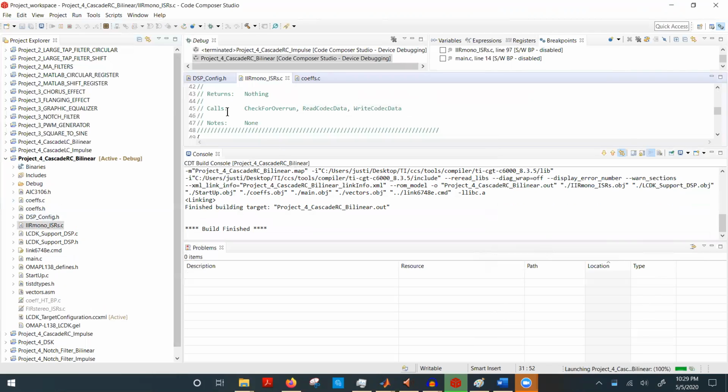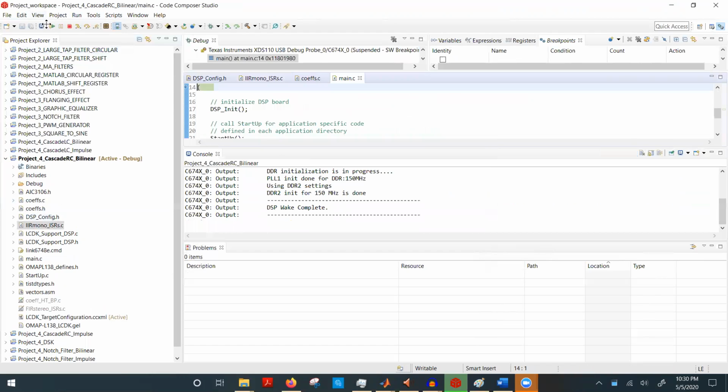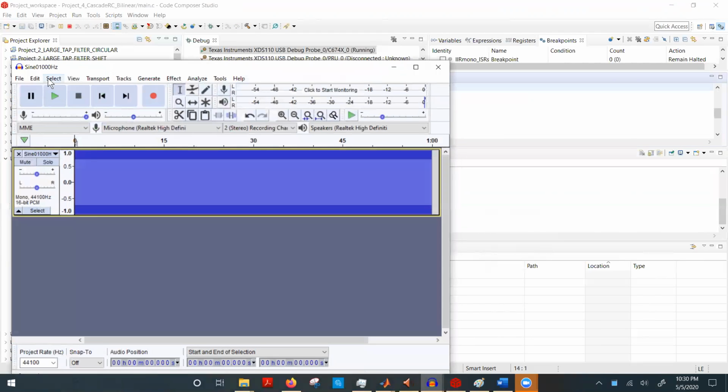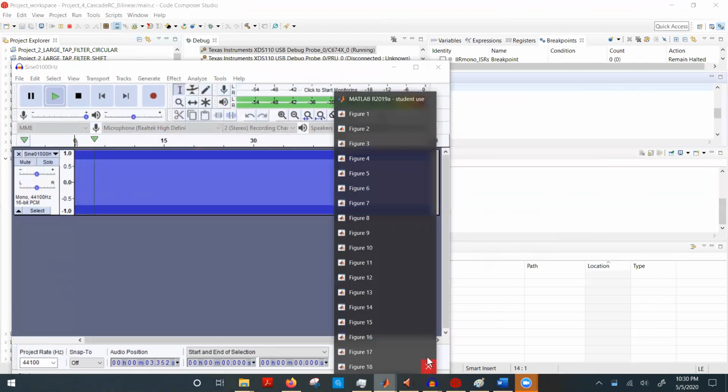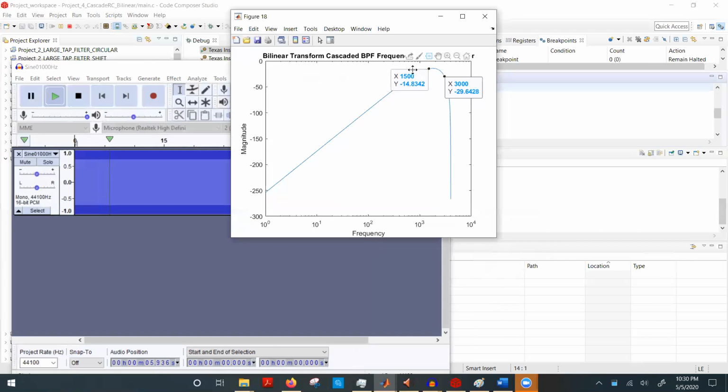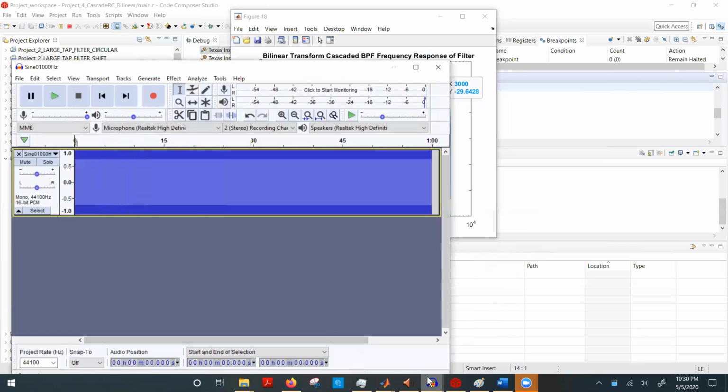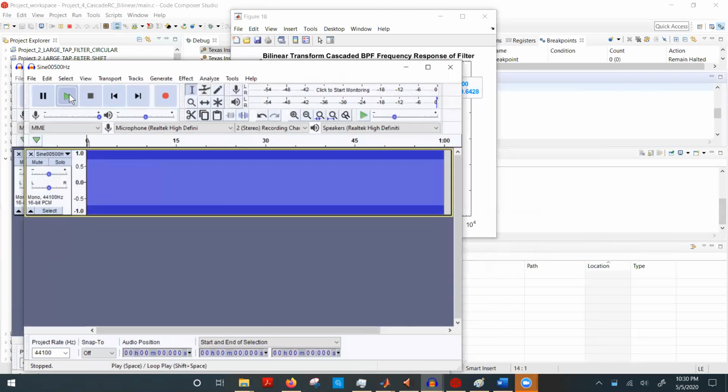All right, so we should be good to go. If I take the 1000 Hz signal, this is slightly attenuated because, like I said earlier, the passband here is from 1500 to 3000, so 1000 is going to be attenuated. If I use a 500 hertz signal, it should be even more attenuated. Yeah, now it's really quiet. This is at max volume. You can barely hear it over the sound of my computer's fan. So this is with that attenuated.